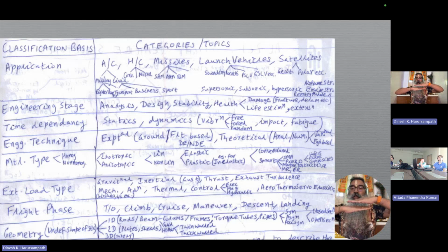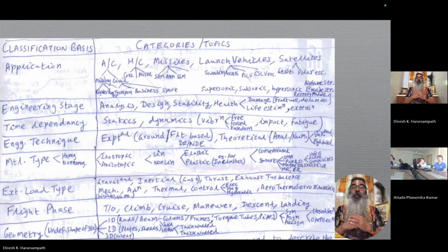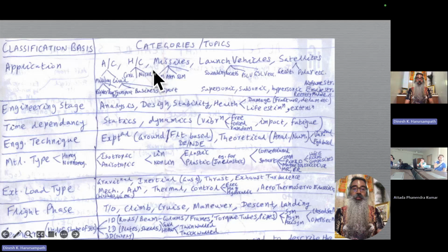Or you could have coaxial rotors, one above the other, both rotating in opposite directions, each causing a torque in a different direction, and therefore, once again, the fuselage will not be affected by the torque. Then you could also have, instead of the tail rotor, this particular configuration, what I call NOTAR, based on McDonnell Douglas nomenclature. McDonnell Douglas, of course, was an aircraft company which was acquired a few decades ago by Boeing,